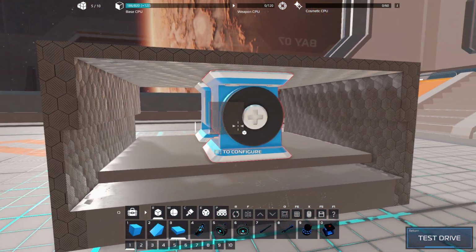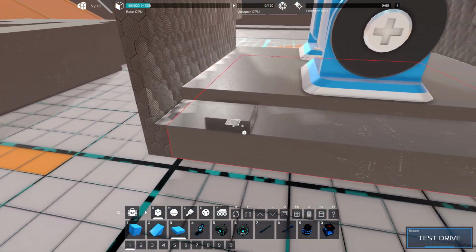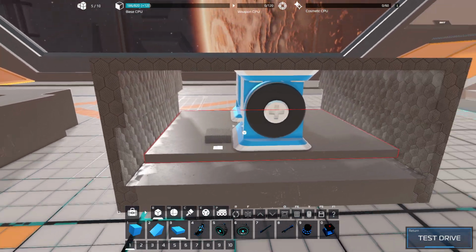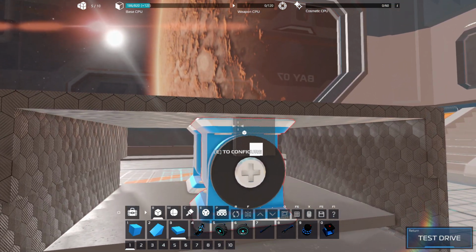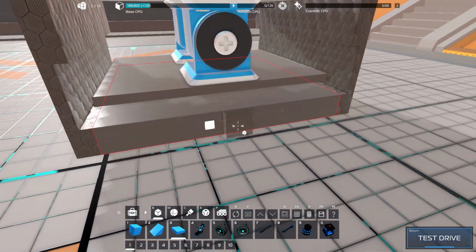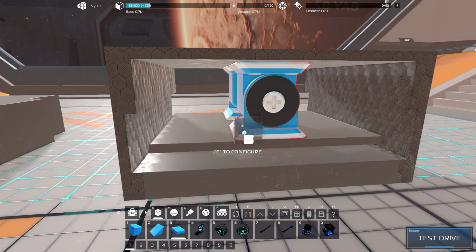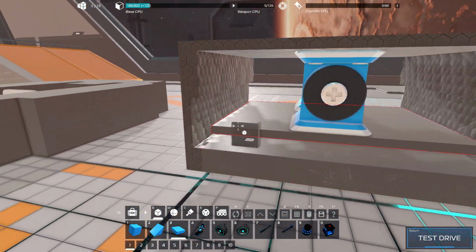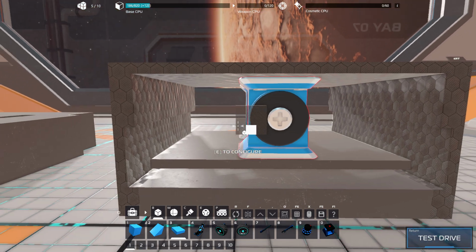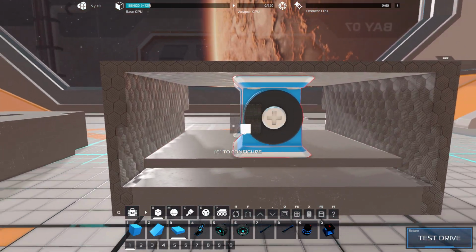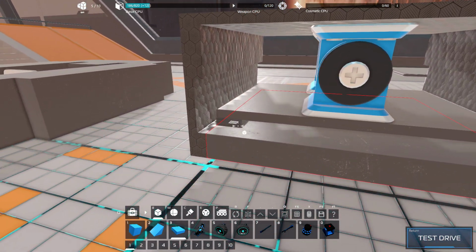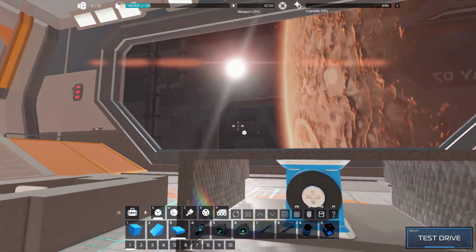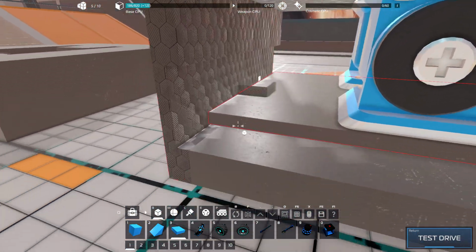So basically what's happening here is the hinges tip this plate against this other plate, and it exerts a force here, and then I think also a force gets exerted back up here on the hinge. And technically the structure should be rigid and it should cancel all that out, and you shouldn't get any excess moments or force, but it ends up generating a moment around. So this is pointing down, this is pointing up. The mass is here, but the center of rotation, due to the excess force here, ends up being a net clockwise motion if we're looking at it from this direction, and these edges are contacting.